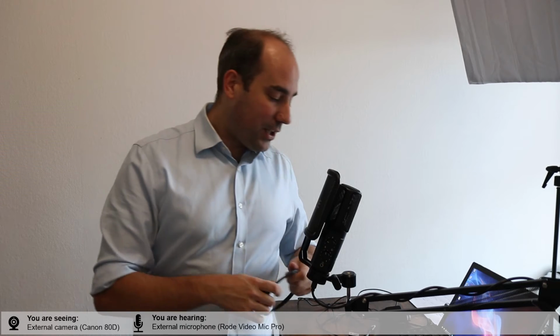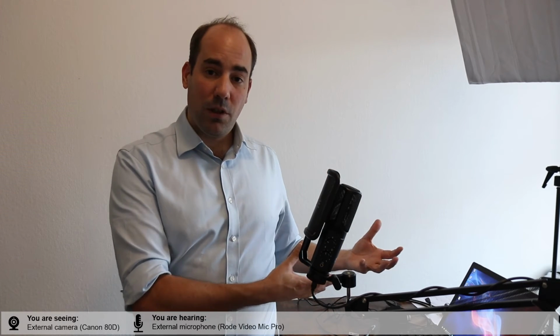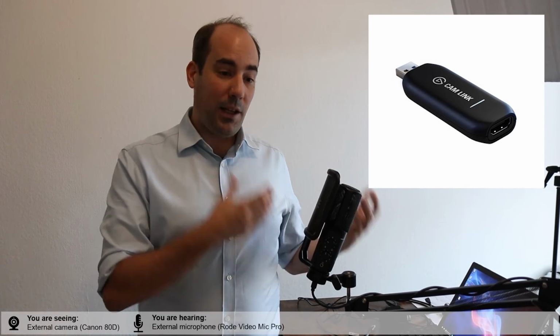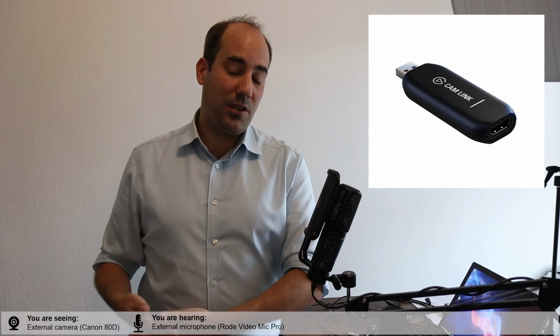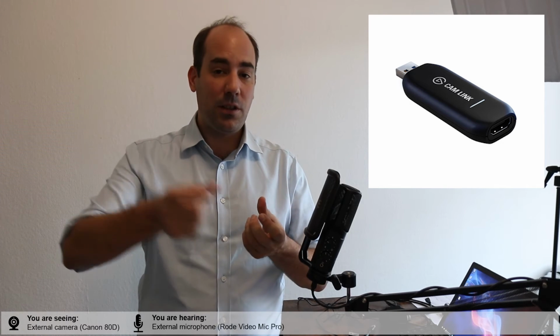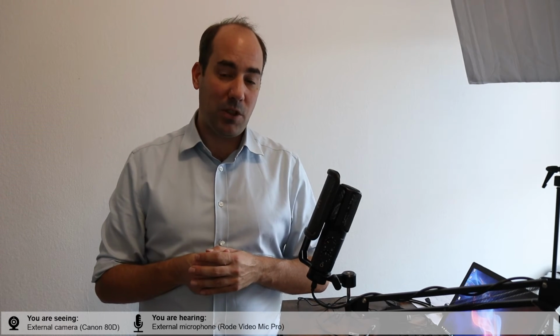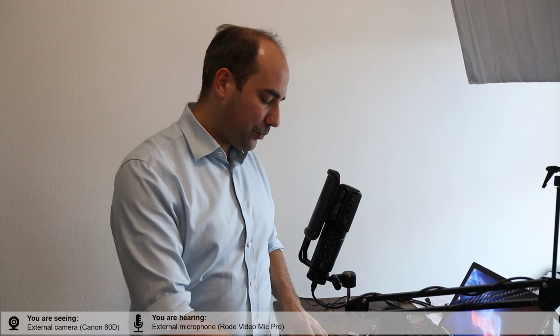The next step in the chain is to convert that signal into something your computer can use. There's options for that. We call them HDMI capture cards or HDMI converters, and they convert an HDMI video signal into a digital signal. So CamLink is the one I'm using, and on the one hand HDMI goes in, on the other side USB comes out. So you plug it into your computer and it will emulate your camera feed as a webcam in your computer, and you can just select that in your software.